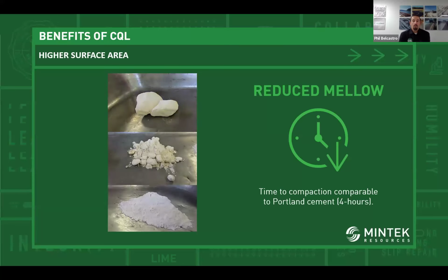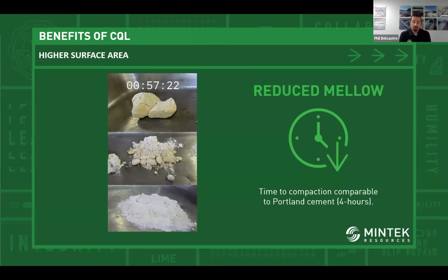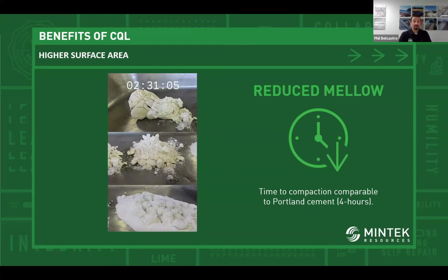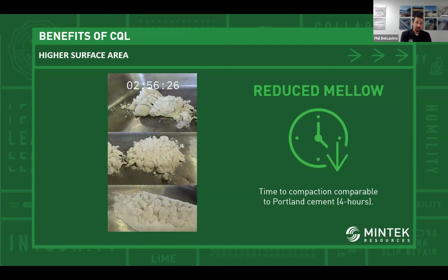So what we've seen since we've decreased the size of those particles is we don't need nearly as much time as we once did, especially because we are also seeing some advancement in the equipment that we're using to incorporate the lime in the soil. Those soil reclaimers have a violent mixing chamber. They've got those teeth in there. Things are happening. Particles are breaking down. We can inject water right in that mixing chamber. That hydration can happen essentially immediately, especially now with our CQL product that is that much finer.